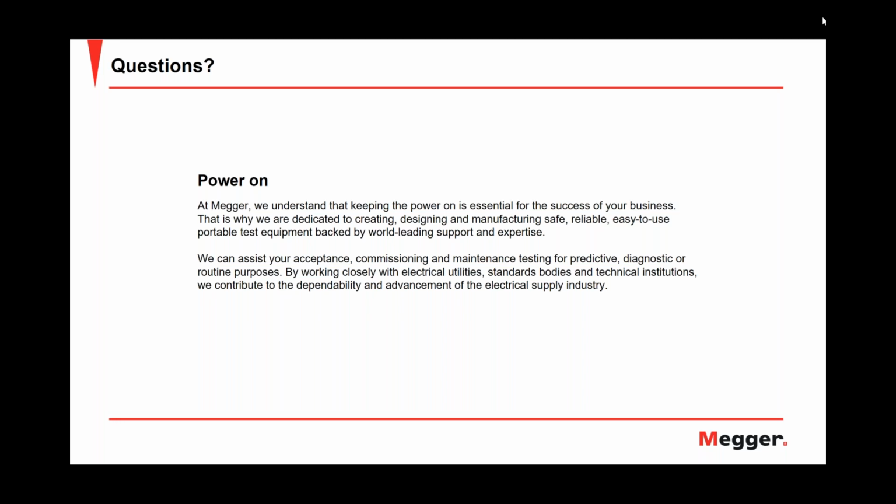Well, overall, I think it's fair to say the more effective cable test is an AC test, simply because you have changing polarity. That change in polarity happens at such a fast rate, like 8 milliseconds or whatever, it puts a lot of stress on the cable. It's not just the voltage stress, it's also the change in the voltage over time that stresses the cable quite a bit. When you compare a DC test to an AC test, which today is basically a VLF test, and you use the same voltage, let's say 20 kV DC and a peak voltage of 20 kV AC, the AC test would flush out more problems in the cable than the DC, because it's a higher stress.